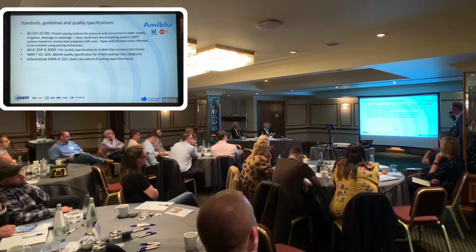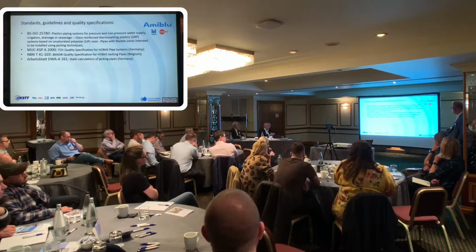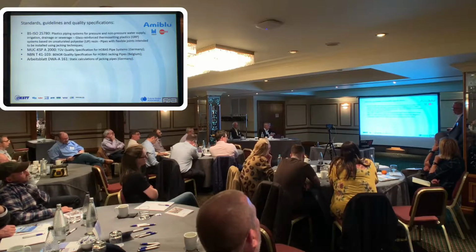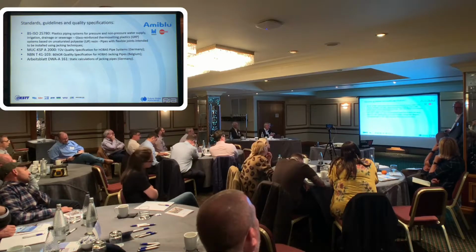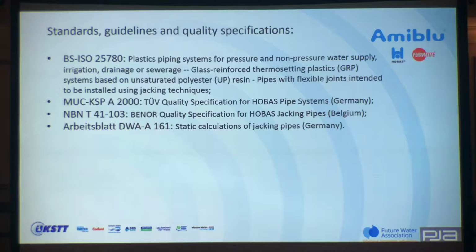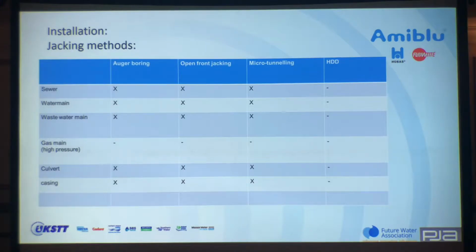And the last one is about static calculations. The ATV-A 161 from Germany is the most advanced guideline at this moment for calculating jacking pipes. It covers the jacking loads, but also the permanent loads and the live loads, like railway loads and aircraft loads.